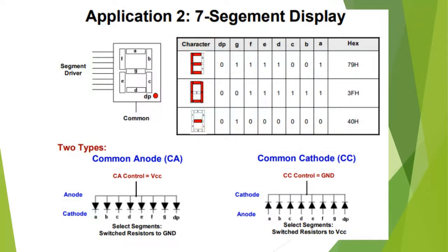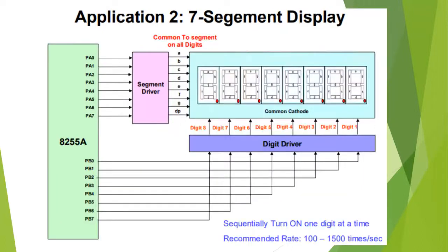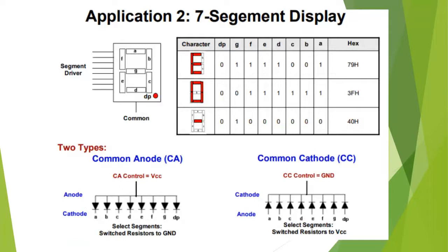And also another thing is, we already know it, this 7-segment display may be common cathode type or common anode type. You know what is called common cathode, common anode type? Common anode: LEDs have anode and cathode, so all the anodes are together. It's common, so it is connected to the VCC. If you send 0 here to A, then this LED is on. If you send 0 here, then LED B is on, C on. That means to turn on any LED, we have to send 0 for common anode system.